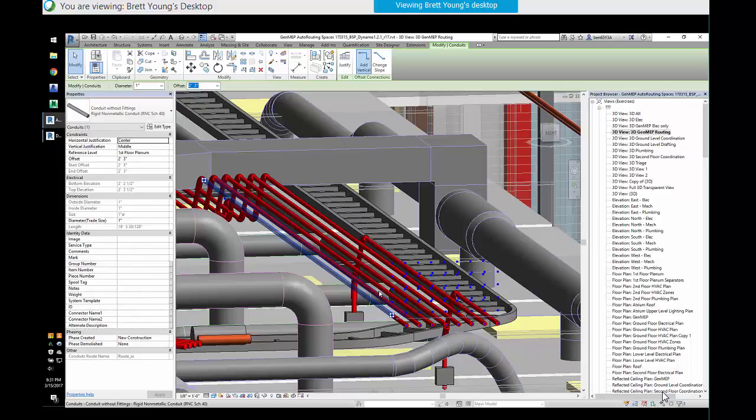But the steel's in the way. It turns out in this example that there's not enough room above the duct and below the steel to work its way through that way. So Ben, using the Dynamo, defined all these points here, and then went through and fit tested every elevation here at looks like about a 3 or 4 inch iteration, right? And then we scored it again using Dynamo to come up with the most optimum group, the most optimum starting elevation for this example.